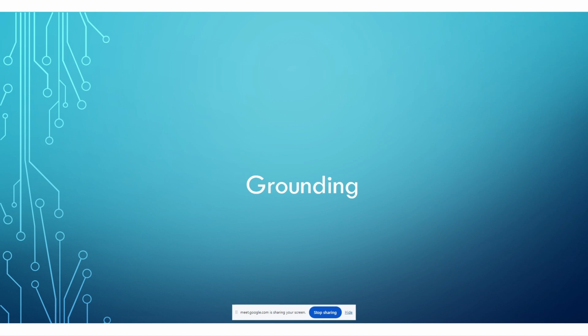So the power integrity aspect, I think, gets rightfully overlooked in mixed signal PCBs. Mixed signal PCBs tend to be operating at lower edge rates. They tend to be operating at lower frequencies. You don't necessarily need to have large ground planes on multiple layers directly next to power planes in order to provide stable power.